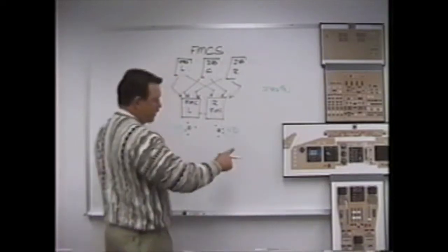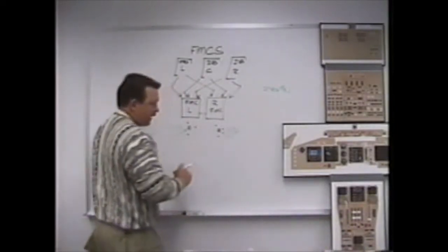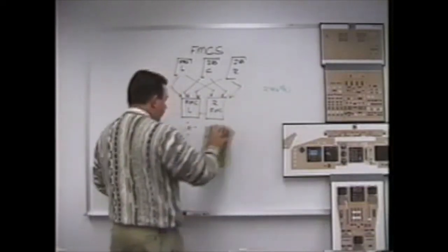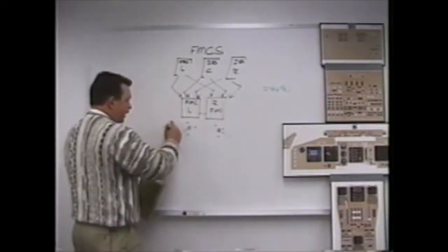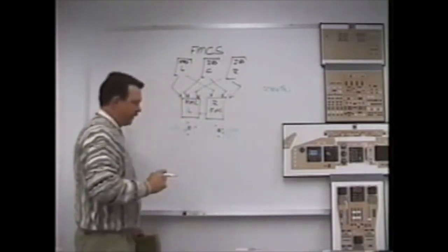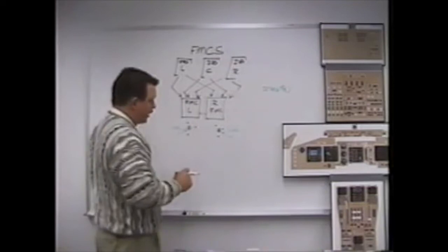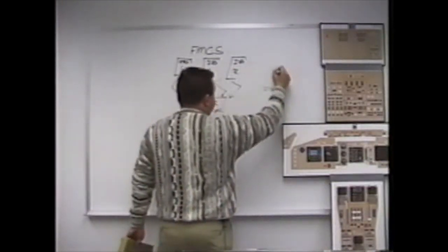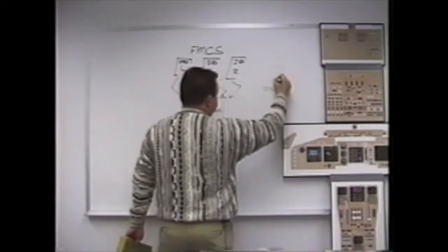If it has a single station, it'll use azimuth and DME off of that station. Finally, towards the end of the flight, probably the only thing other than GPS you'll ever see is loc, because coming down final, it might like the localizer reference a little better for update information. The FMC gets to choose which of those it uses.